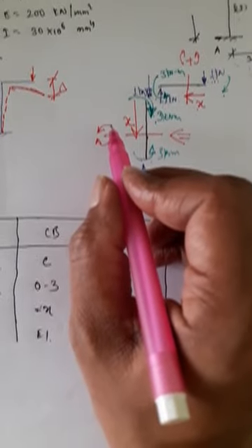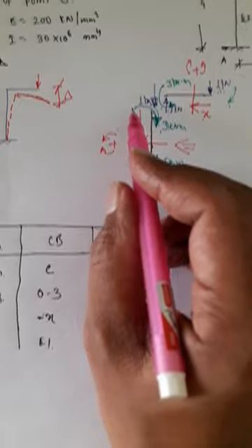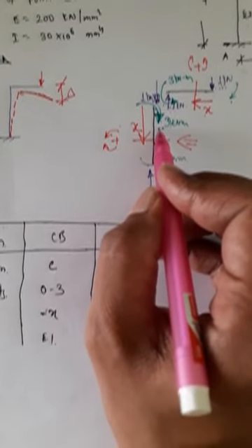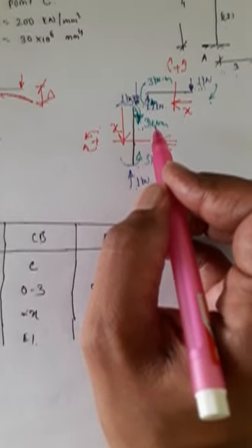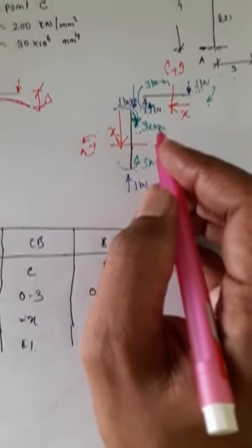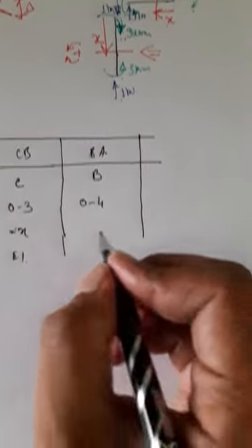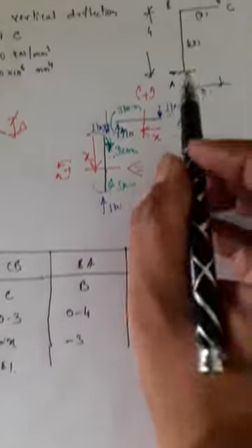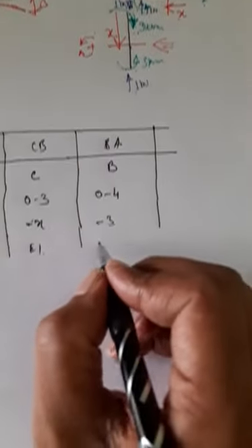When you are looking at this direction, right hand side anti-clockwise is positive and this couple is acting clockwise. So minus 3. Distance does not come into picture. For couple, you have to take the values directly. So its value will be minus 3. EI is 2I, hence you write here 2EI.